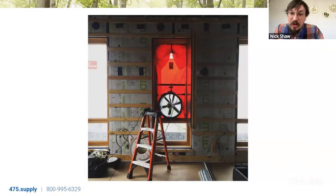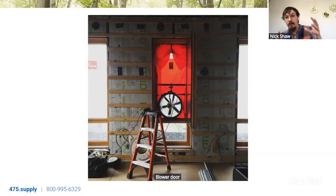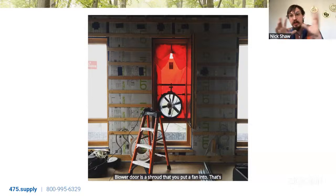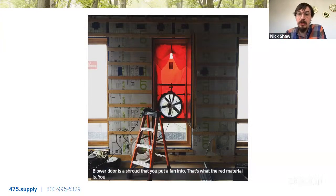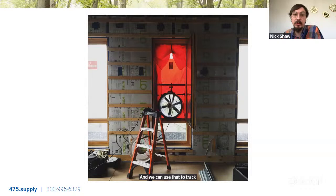We always want a blower door test. That's the best way to play quality control. Blower door is a shroud that you put a fan into. That's what the red material is. You set that up to an exterior window or door, and then that fan pressurizes or depressurizes the building envelope, so you can measure literally how airtight the project is on the job site. And we can use that to track and find air leaks and make the project even more airtight.